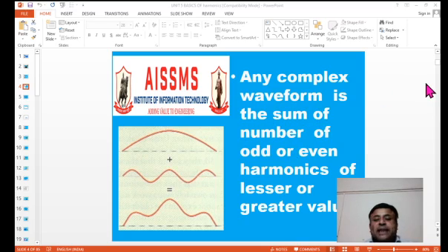Now as you know, we are having sinusoidal input to a number of devices. If you are giving this type of distorted wave, then it will have erroneous operation. It will maloperate. The equipment to which we are applying such a wave will be maloperating because modern electronic devices and circuits are designed for a pure sine wave. In the absence of a pure sine wave, it will cause misbehavior like undue tripping of transformers or breakers and a number of such things.